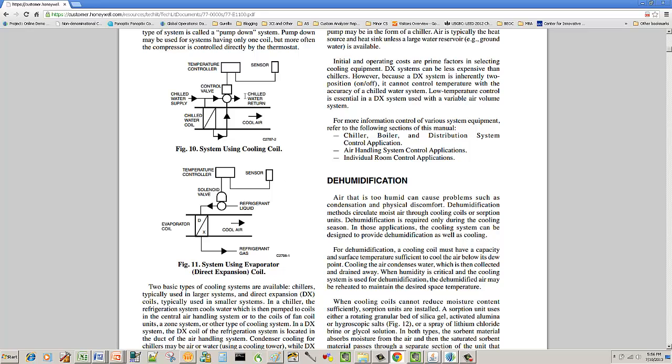It's the same thing you'll see when we move into cooling towers. We take advantage of a latent change, and that allows us to remove massive amounts of BTUs. We take advantage of the fact that refrigerant changes states at different temperatures. For example, when it compresses to a liquid and evaporates to a gas, those are at different thresholds based off of the refrigerant types. So that allows you to do things.